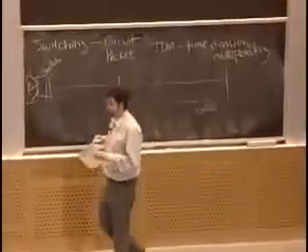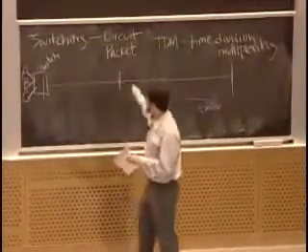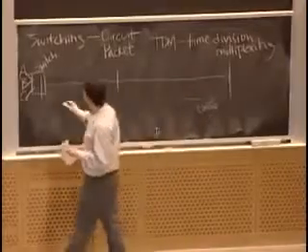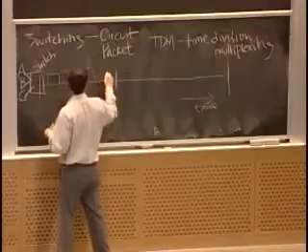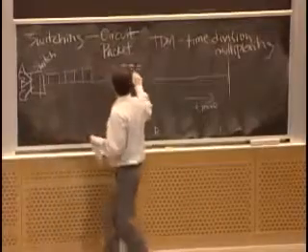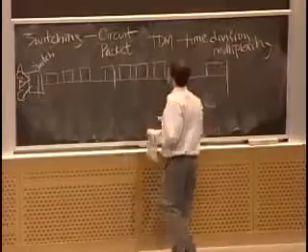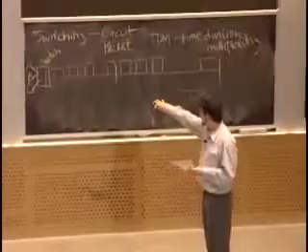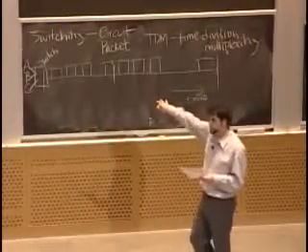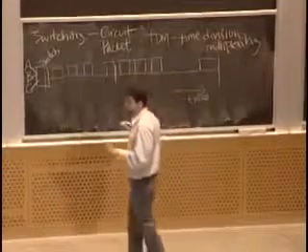If you were to look at all the different messages that are on the wire, what you would see is a repeating pattern of time intervals. And each of these time intervals would be carved up into a number of slots. Okay, and each slot is allocated to exactly one of these nodes, and each node gets the same slot in each one of these larger intervals.